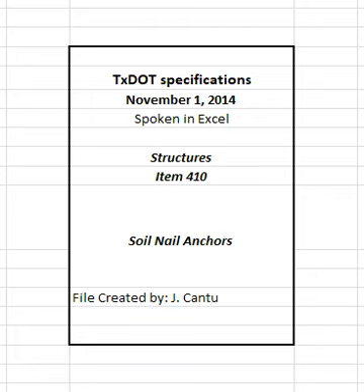The need for stiffer grout may arise when the hollow stem auger drilling method is used or it is desired to control leakage of grout into highly permeable granular soils or highly fractured rock. In these instances, the engineer may waive the requirements of slump flow testing. 2.2 Pneumatically placed concrete. Use materials that meet the requirements of Class II concrete in item 431, pneumatically placed concrete, unless otherwise shown on the plans.